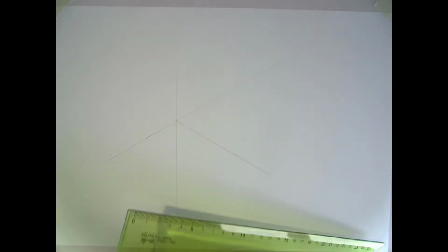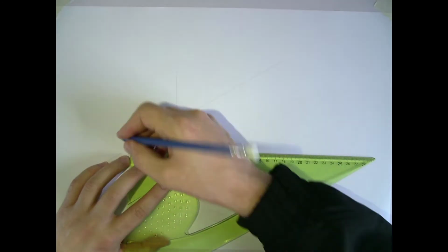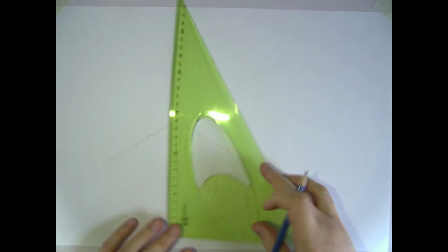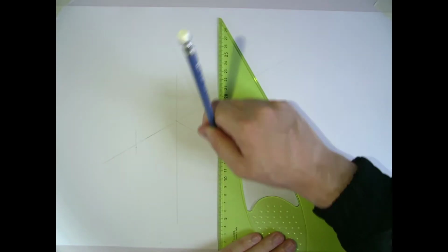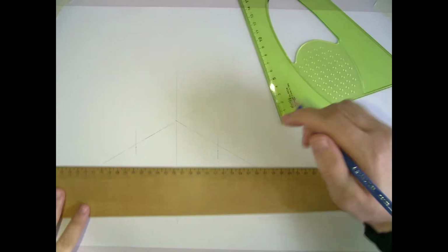And Part A is to draw the equilateral triangle and the axonometric axis. So I've started by drawing my axis. They are at 30 degrees. It's located approximately halfway up the page, just to give us space for the plan and for the elevation that's going to go over here. We're told that the side length of the line AB, which is part of the equilateral triangle, is 100 mil. So it's going to be 50 millimeters either side of the vertical axis line. And when drawn accurately, they line up with each other. They're horizontal.